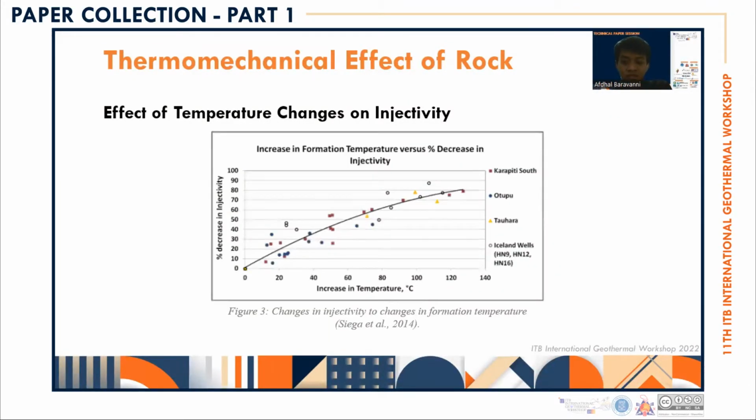Based on observation made at the Wairakei Tauhara geothermal field by Sagar, Sagar developed an empirical technique to adjust the injectivity for the fluid injection temperature. The completion test data after drilling and injection data from 21 injection wells in 3 different areas in the Wairakei Tauhara field were then analyzed to observe changes in injectivity.